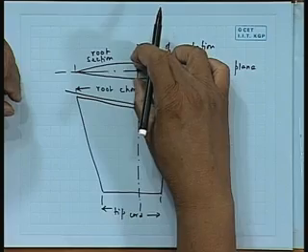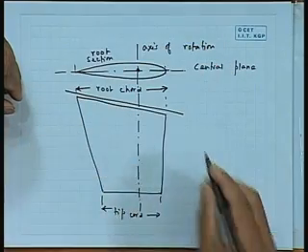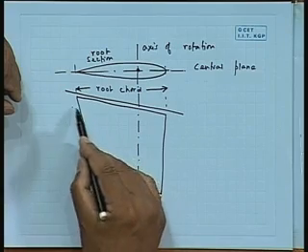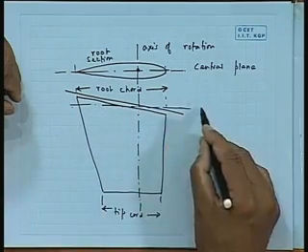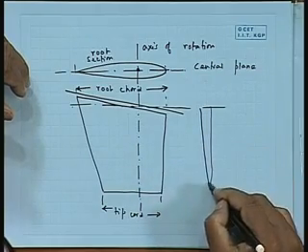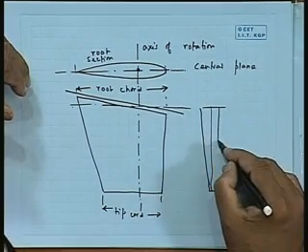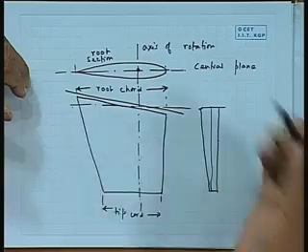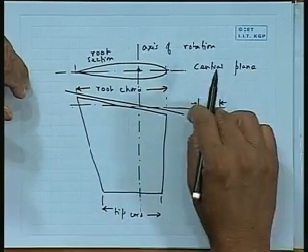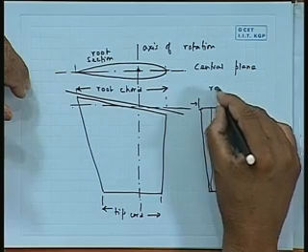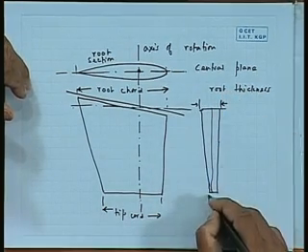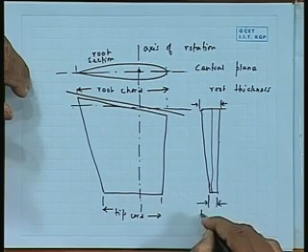Okay. Now, actually, in fact, we should draw a line here also, the mean line. If you see here, the rudder will be looking something like that. You know, the thickness also comes down as you go down. There is a thickness here. This is my mean root thickness. This will of course be my tip thickness.